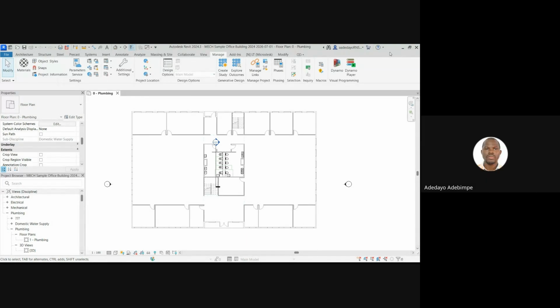Okay, Engineer Victor, thank you very much for that question. The way Revit officially will tell you to load in a family is to go to your Insert, Load Family, then bring it in. The reason is that you have different types of family. If we're using a family with a type catalog, dragging it in might be a challenge, because dragging it in will just bring in everything.